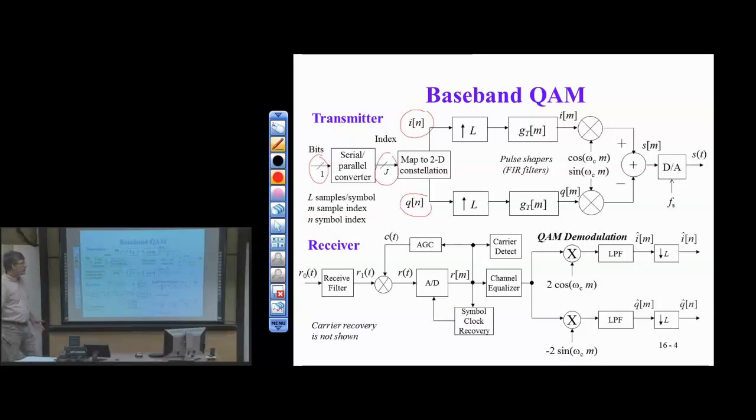And because it's quadrature amplitude modulation, we have to have up conversion. This allows us to put 2 PAM signals in the same transmission bandwidth. So we recover this loss of the doubling of transmission bandwidth in up-converted PAM, but now we're putting 2 PAM signals in that same double transmission bandwidth, so we recover back that factor of 2.